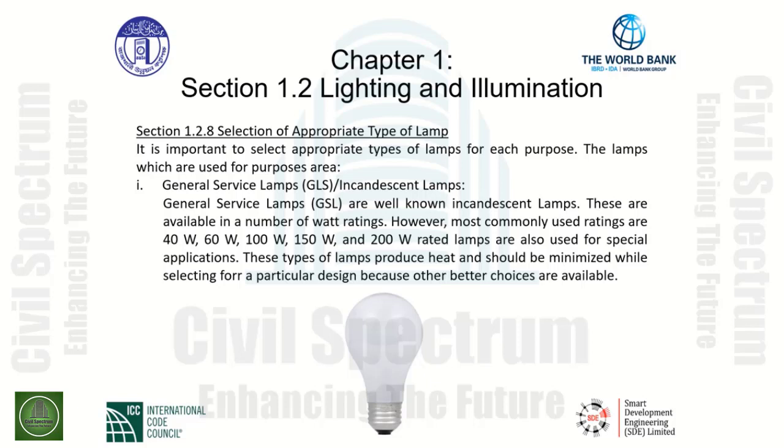However, the most commonly used ratings are 40 watt, 60 watt, 100 watt, 150 watt, and 200 watt rated lamps are also used for special applications. These types of lamps produce heat and should be minimized while selecting for a particular design because other better choices are available. These types of bulbs contain a filament inside the bulb that is heated via electric power until it glows. The purpose of the bulb is to encapsulate the filament to protect it from oxygen as it would oxidize.